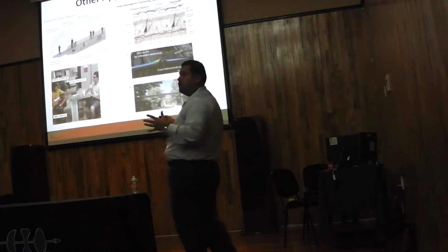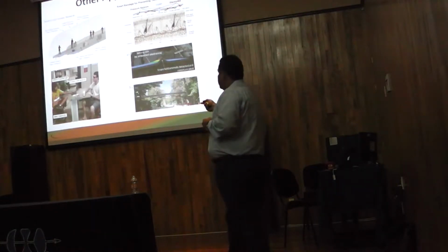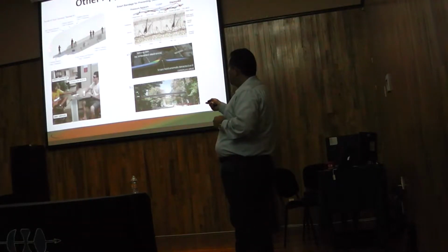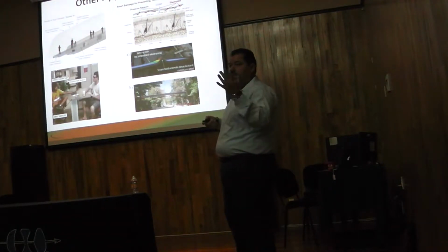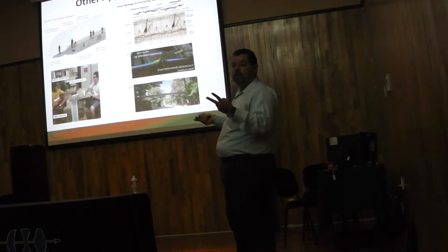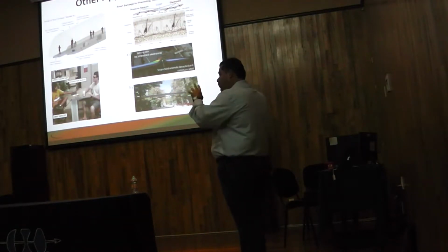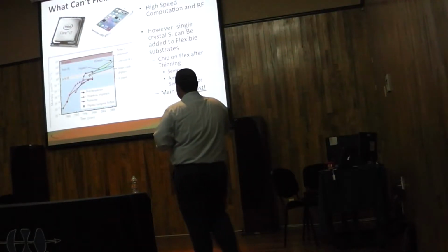Why is flexible electronics relevant here? Because it's a large area, right? So if we need to make this tunnel out of silicon, it's going to be very expensive. Number one. Number two, silicon is very sensitive to gamma, so we have false positives. So there are a lot of things that hopefully I will convince you that our material is better.